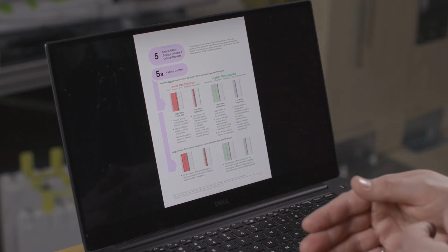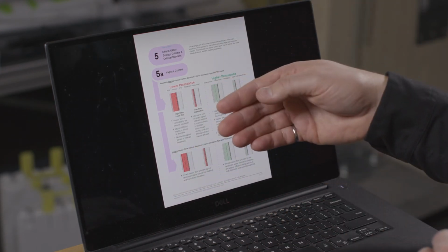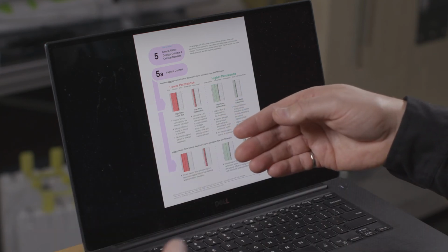And the vapor flow control guidance is different. If you have a lot of exterior insulation, the exterior insulation is entirely controlling the vapor flow. If you have a little bit of insulation, you might not have enough insulation to warm that sheathing up enough, and that's what the ratio is looking at, and therefore you may need some vapor control on the inside. And that's entirely what this table is walking through. So I encourage you to walk through some of your own examples here to look at high and low ratio. Both can work.